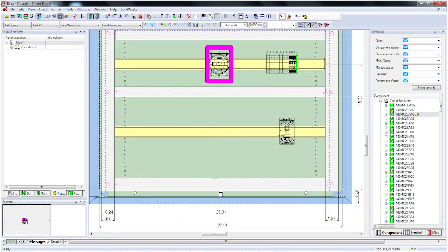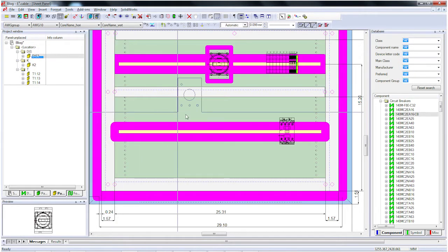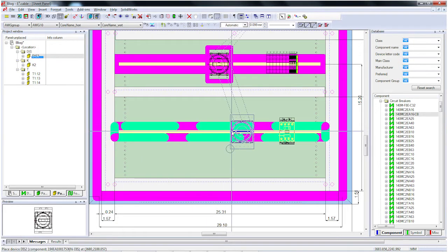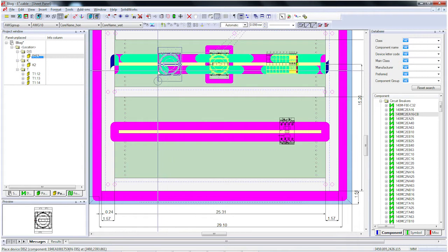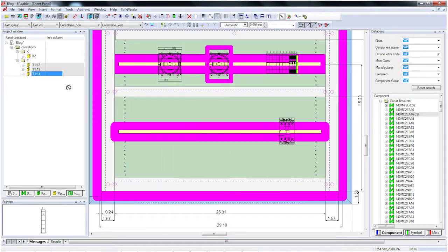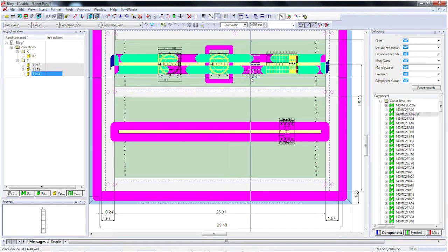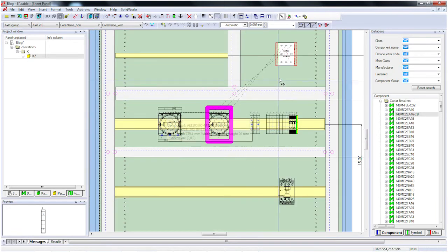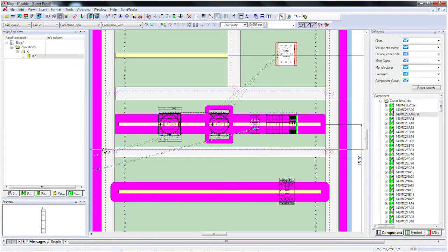All the devices that need to be placed in the panel are easily managed in this Panel Unplaced tab, which I like to refer to as a to-do list. You can just drag and drop the devices in the desired locations. And as you're placing these devices, E3 is guiding you by showing you these logic lines referenced from the schematics to optimize the panel design.